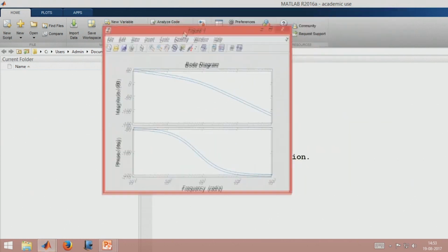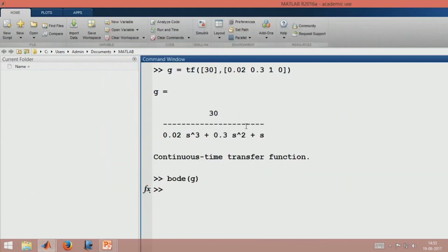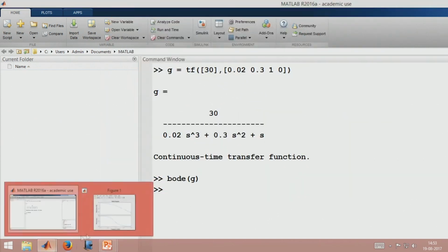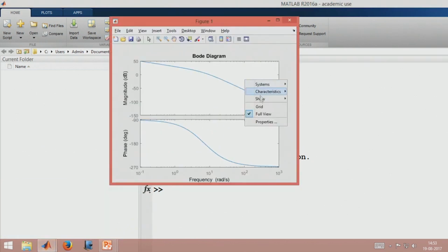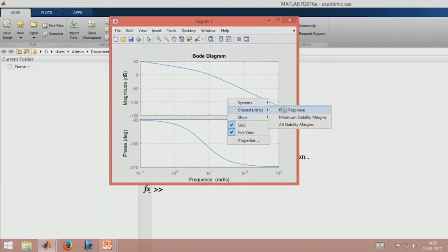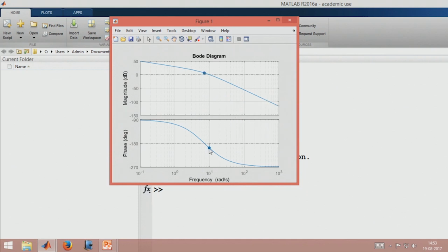Okay, so I have the plot here. I'll see via the grid the characteristic stability margins. I have a phase margin of -17, a negative gain margin, and it shows that the closed loop system is unstable. So something not very good has happened here.